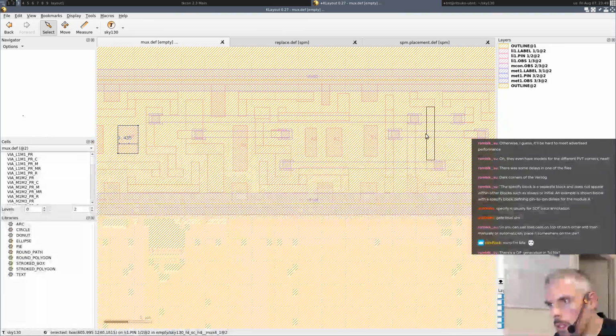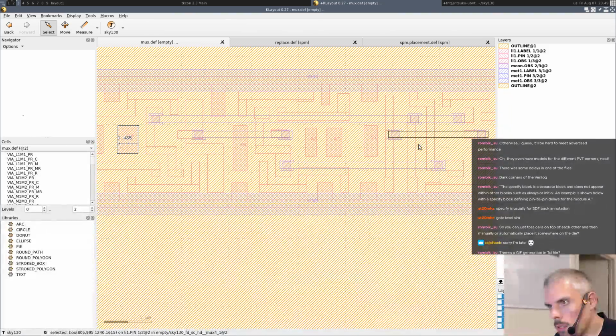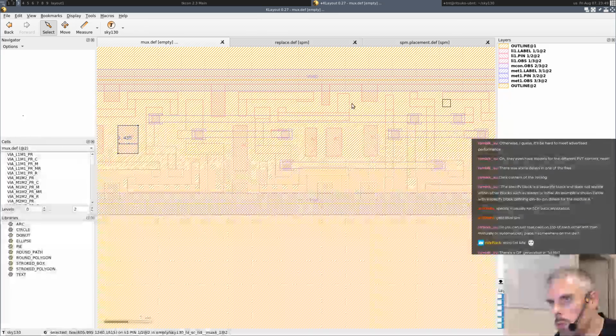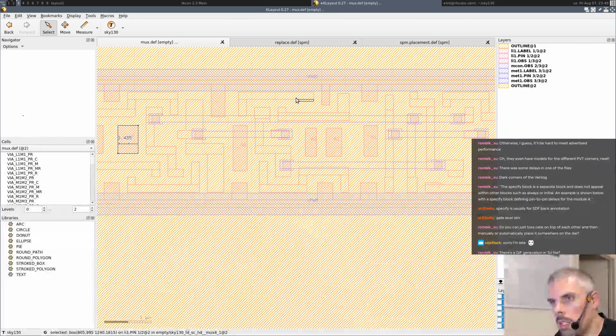So the spacing between here and here and here and here, so here is twice the space, so that you actually have a place to run another wire here, and you have one more here and one more here. And so you have 1, 2, 3, 4, 5, 6 kind of spots equidistant to run wires, and then you have the power rails kind of take up a space.